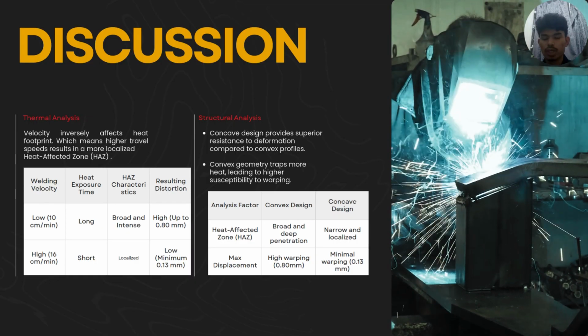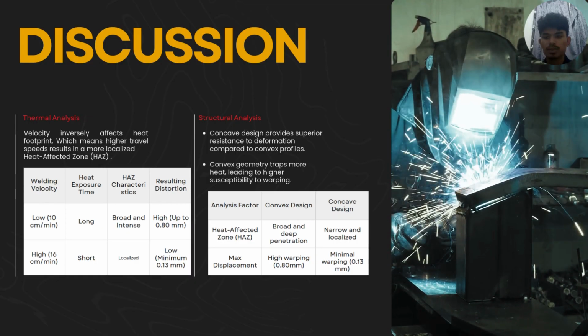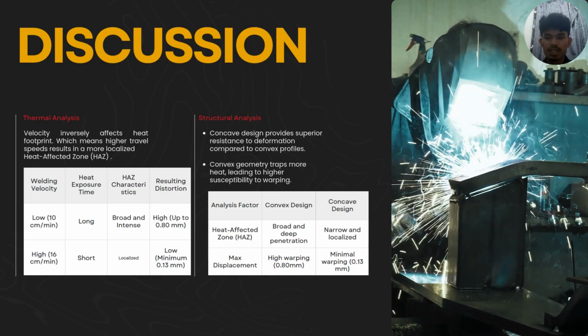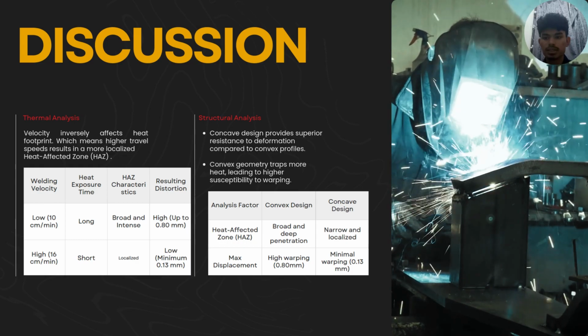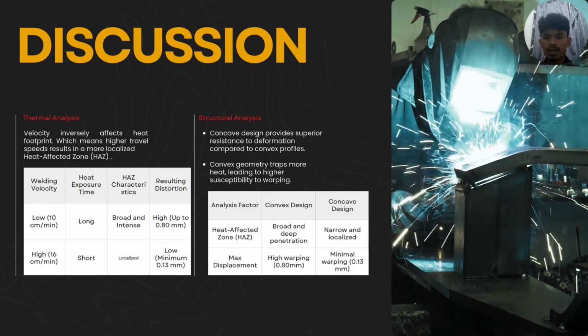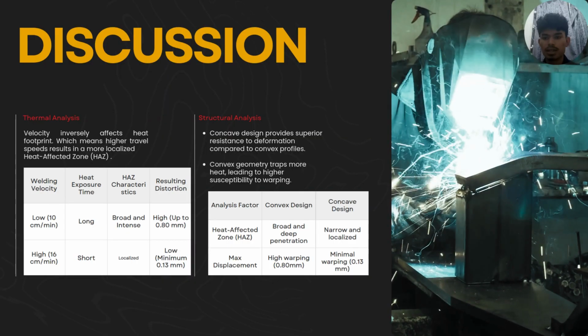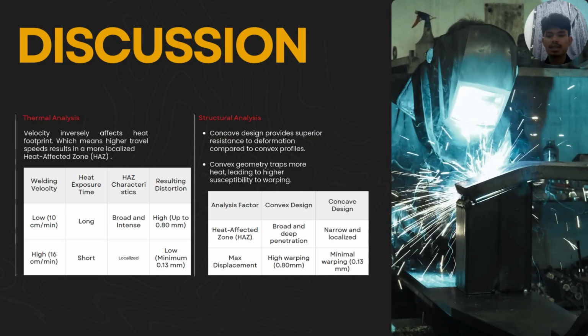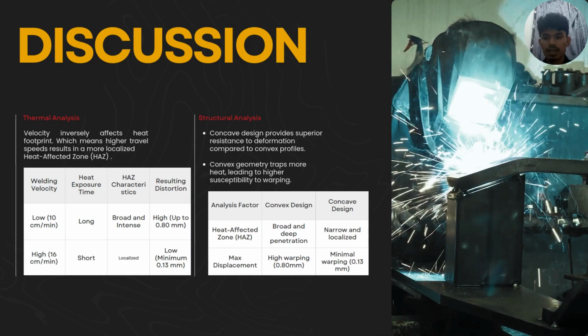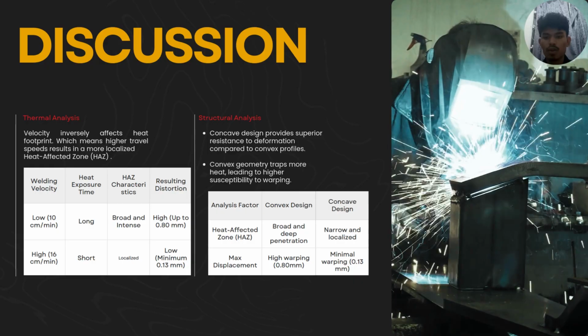When we look at the table, there are analysis factor, convex design, and concave design. For the HAZ, the convex design has broad and deep penetration, different from the concave, which only has narrow and localized.